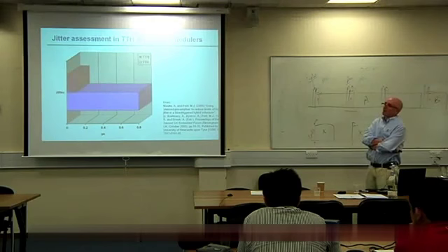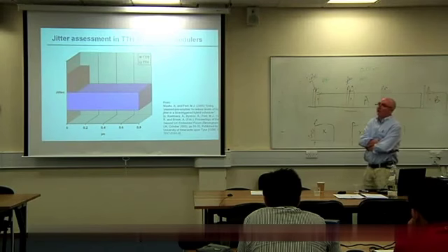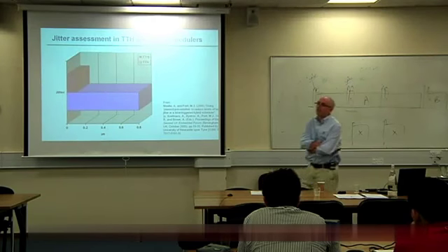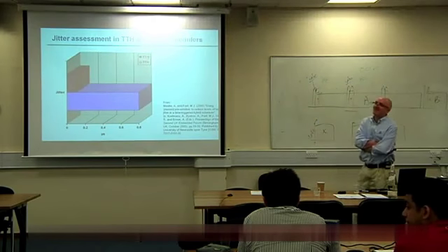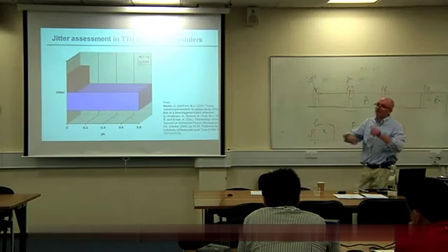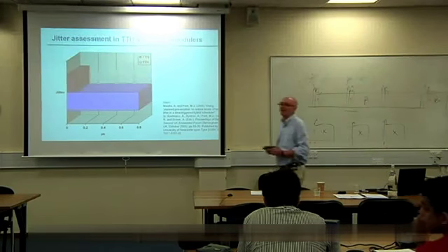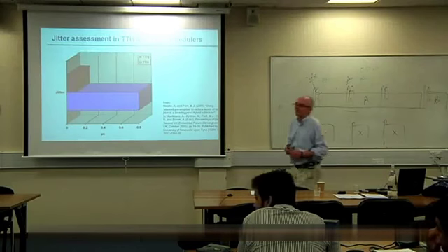Okay, so what instructions are you using to check whether the tick count is equal to 1 or not? So you're going to go through a set of non-equivalent instructions, so it can't be all NOPs because you've got some instructions that are checking the flag. You can work that out, so you're going to know how long that takes. It's going to be the same every time.